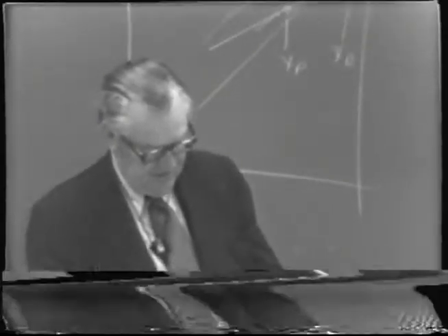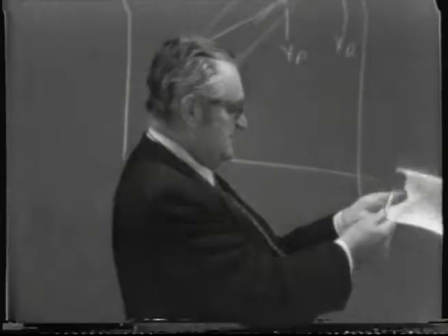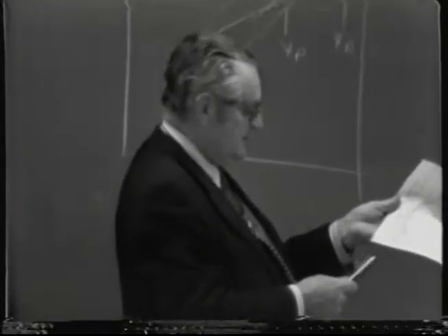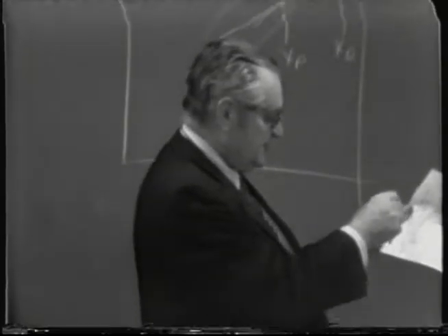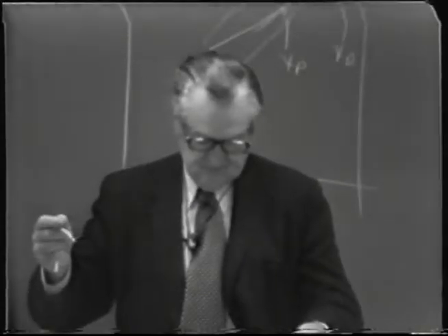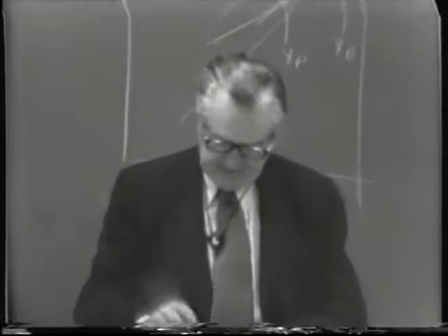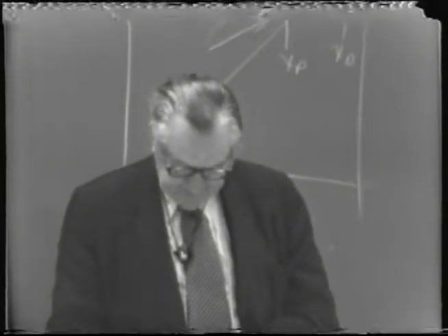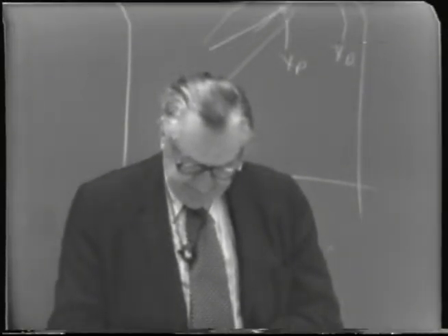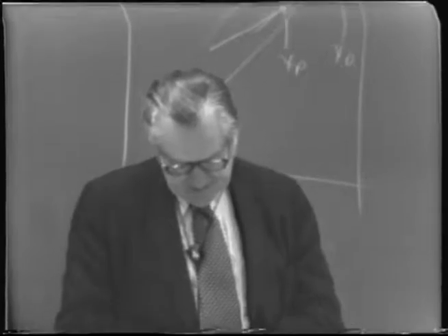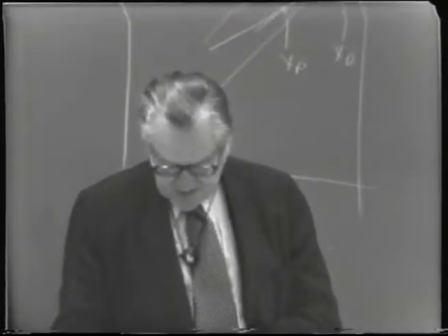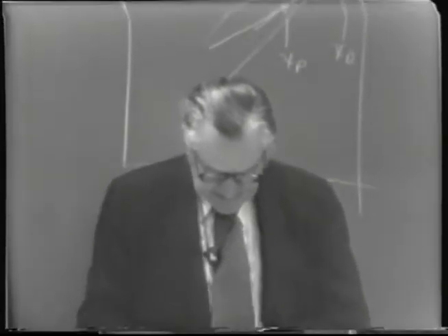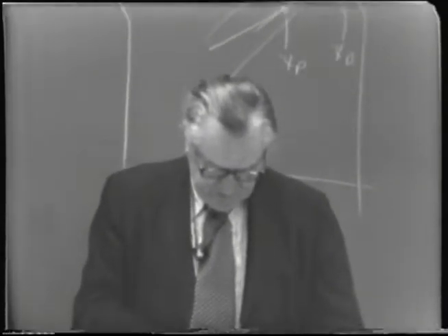Or another way is to simply translate this point of intersection of the Q line and the operating line in the concentrating section, read off the points and relocate it. Then we can draw the operating line in the stripping section from the point of intersection of the Q line and the rectifying section line down to X sub B on the x-axis of 0.00124.